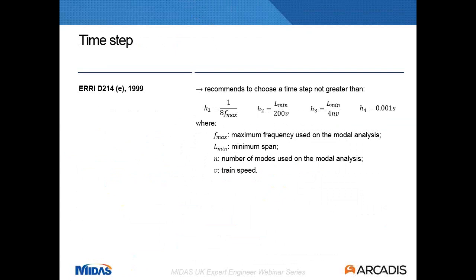And you should use the minimum timestep of these 4 values. These formulas depend on the frequencies that you have extracted from your eigenvalue analysis, the span of your bridge, the fundamental frequency, and well, the last of them all is that you shouldn't use a timestep that is over 1 millisecond.